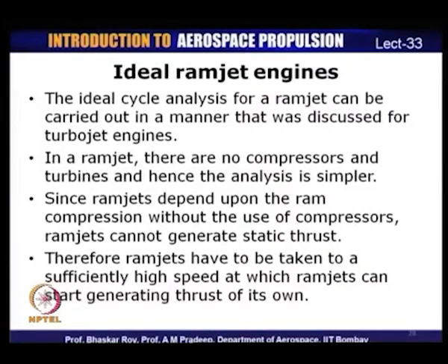And as I have already mentioned, since ramjets depend upon the ram compression in the intake without the use of compressors, they cannot generate any static thrust. Ramjets have to be taken to a reasonably high Mach number before they begin to generate thrust, and so they cannot really start from 0 Mach number and start operating. They have to be flown to a certain Mach number before ramjets begin to operate. So, I will not discuss the ramjet cycle analysis in detail because it is a lot simpler and something we have already discussed for a lot of other types of cycles.